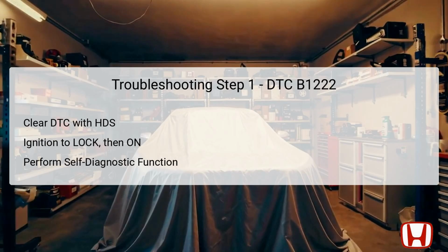Following that, perform the self-diagnostic function using the HDS, checking the HVAC, heating, ventilation, and air conditioning control unit or the climate control unit itself. This function provides crucial insight into operational status and aids in confirming whether the same DTC appears again. By performing these preliminary actions, technicians can effectively assess the necessity for further troubleshooting and zero in on specific problems within the climate control system.